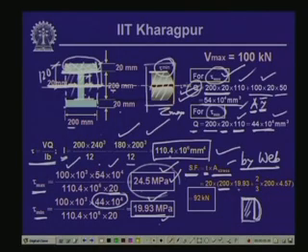So, 200 times 19.93, the minimum value of the shearing stress, is this rectangular area, and this parabolic area will be 2/3 of this height times this distance. This distance is tau maximum minus tau minimum, that means 24.5 minus 19.93, which gives a value of 4.57. So, 2/3 of 200 times 4.57 is the area of this parabolic part. The whole thing gives us the area of this entire stress diagram.